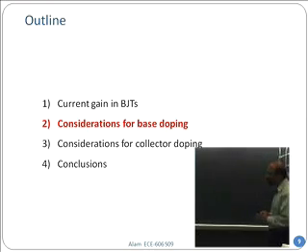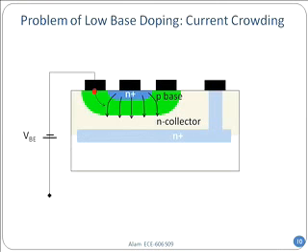So let's see what's wrong in making the base doping small. That's a major problem here. This is what's wrong. The analysis we have done so far is all one-dimensional. We have just assumed that it is a vertical cross-section, a one-dimensional cut. That's not really how a transistor operates. There will be many more surprises when you actually do an actual transistor. By the way, do you realize that this double diffused junction configuration automatically ensures that the emitter will have a higher doping than the base?